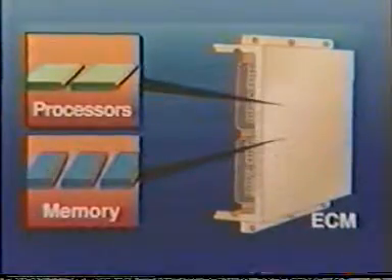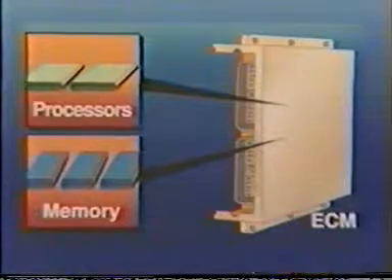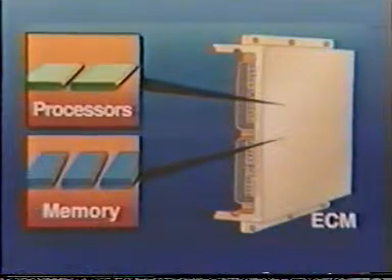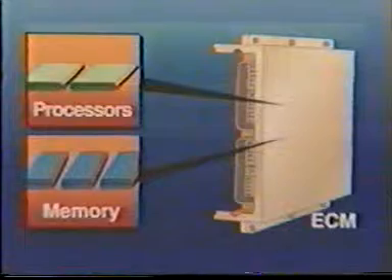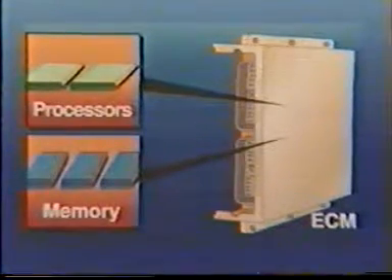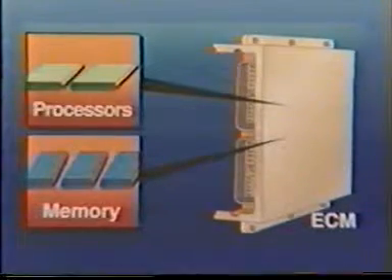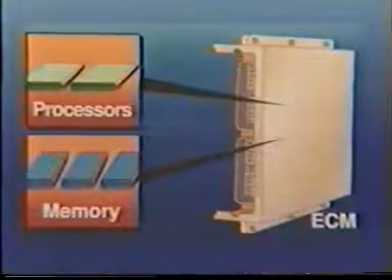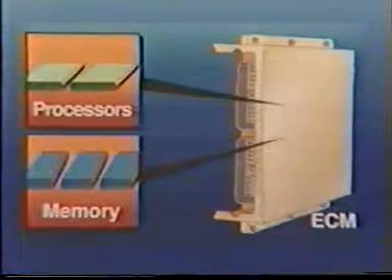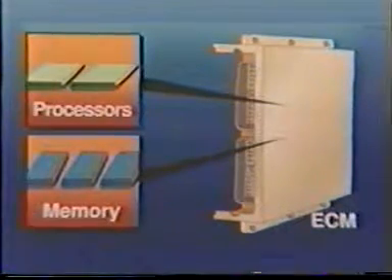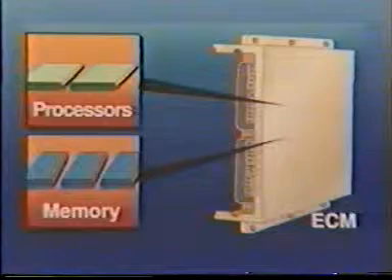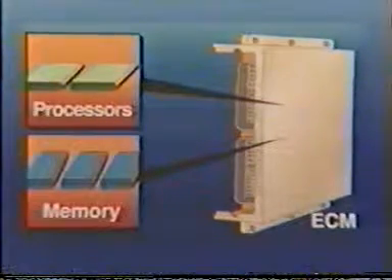The QSK-19, like the other Cummins electronic engines, is commanded by an electronic control module, or ECM. The QSK-19 fuel system ECM contains the latest technology from Cummins Electronics. It has 2 microprocessors to process and manage the data necessary to operate the engine and systems.